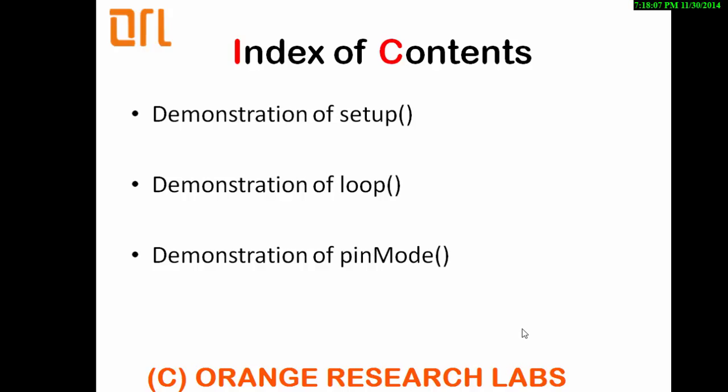Okay, so when you go for Arduino, the program is totally divided into three. One is global declaration section, followed by setup function, followed by loop function. If there are any user defined functions, then you need to define them outside loop. Every C program will have a main function, but you don't find any main function in an Arduino program. The main section in an Arduino program is totally divided into two. One is setup, second one is loop.